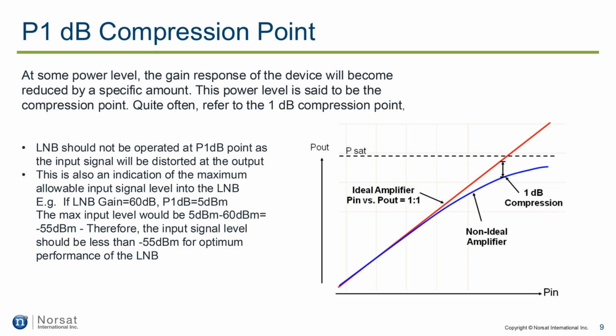at the output. On the other hand, the figure shows the relationship between the input power and the output power. For a small input power, the output power will be increased linearly as it increases in the input power by the gain value. When the output power reaches P1 dB, the signal will compress 1 decibel from the expected value.